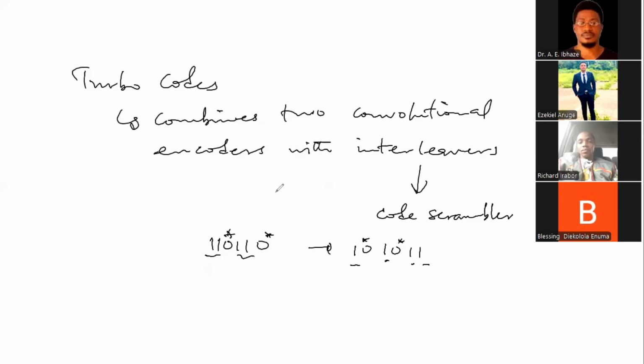And for us to now look up how the turbo code works, because it literally concatenates two convolutional encoders to process the input, okay? And then once that is done, the interleaver scrambles the input bits and feeds it into the next convolutional encoder.